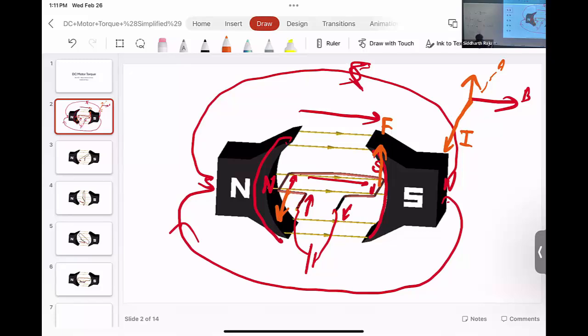If there is some mechanism on which this conductor is pivoted, this is what the pivot would look like, where we have a rotor structure. And we are looking at just one conductor turn. So there is a central pivot over which this thing can rotate. Once we have force, if there is something it's pivoted on, it's going to start to rotate. So what is going to be the force? We have some current I. Let's say the length of this conductor is L. The length would mean this vertical.